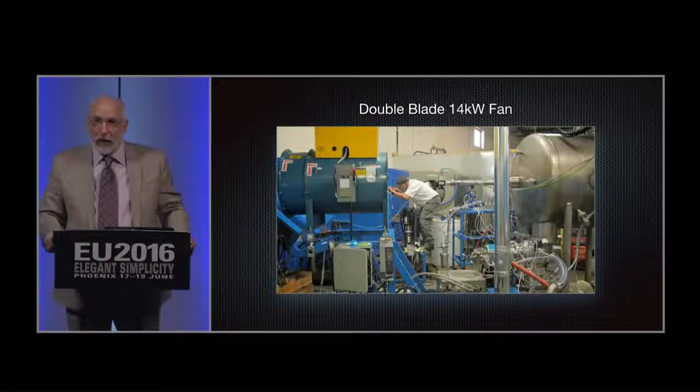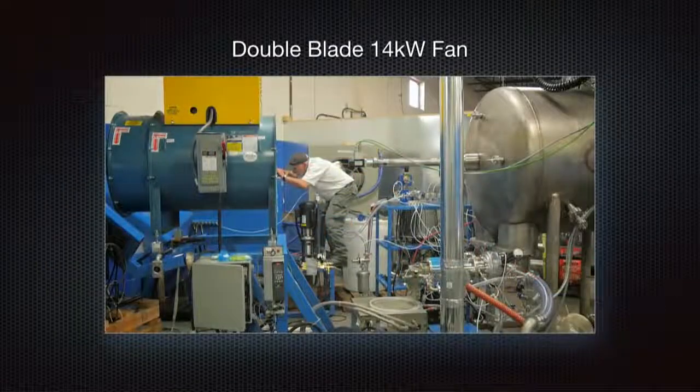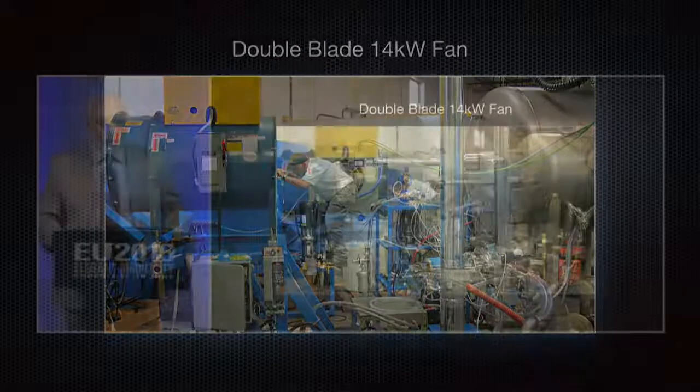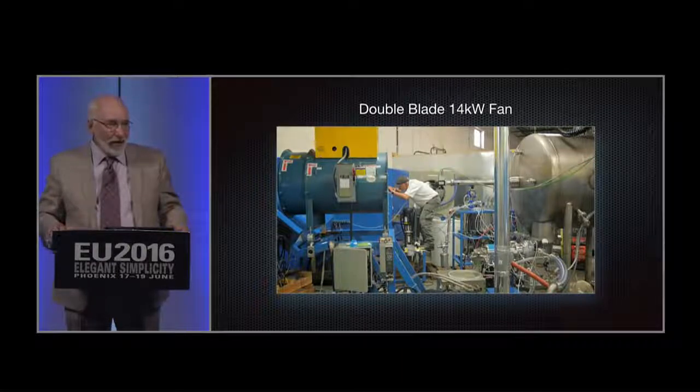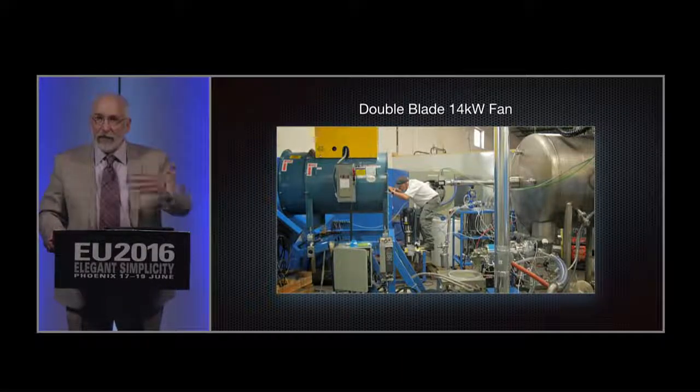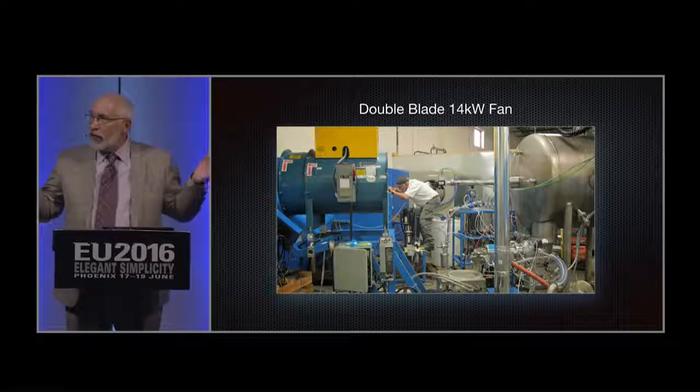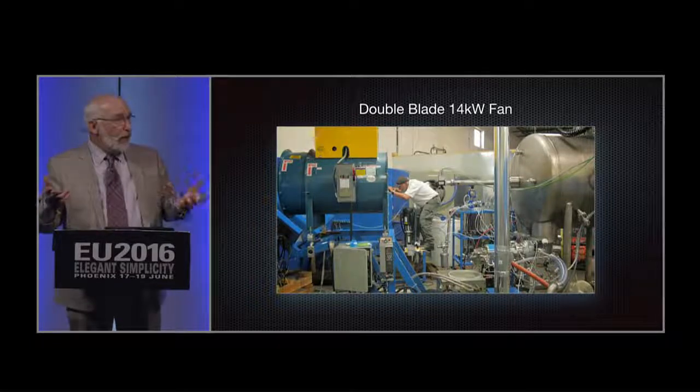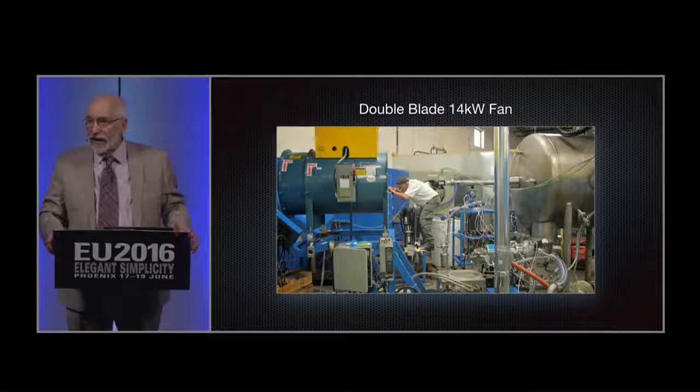So then I thought, well, I need a fan. And that big blue thing is the fan that we came up with. I told Scott that, yes, we have a solution, but what I didn't tell him at the time is just how big a fan we needed. And so he thought, okay, this is good, so we're going to keep moving ahead. And the fan actually will suck about 14,000 cubic feet per minute at a pressure of about 2 inches of, not 2 atmospheres, but 2 inches of water, which basically would suck all the air out of this room in approximately 30 seconds.